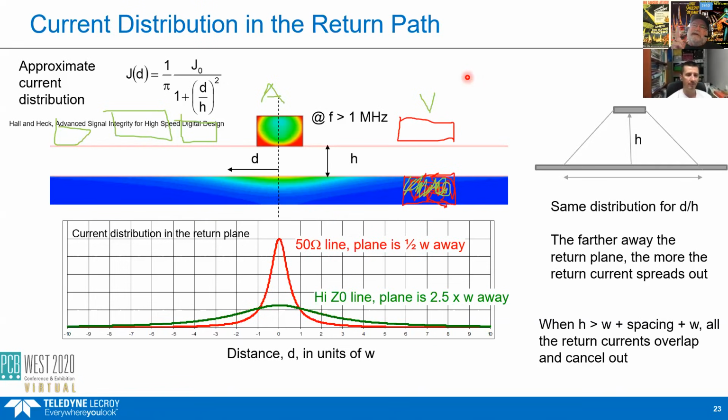Question number 2 is, as I move the traces farther apart, how much crosstalk do I have, and how far apart do I have to get them so that I'm below that threshold, that allocated noise budget for crosstalk. For typical digital systems, microstrip and stripline, assuming 50 ohm lines, if I keep the spacing between the 2 lines greater than twice the line width, that defines a spacing of about 4 times the dielectric thickness for microstrip traces or stripline.